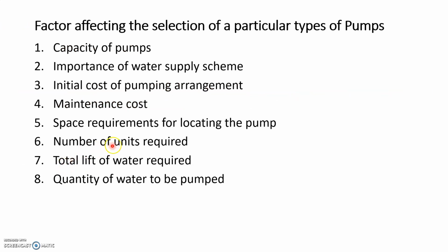Now there are certain factors based on which you have to select the type of pump you require. The first one is based on the capacity, whether capacity is large or small. Then the importance of the water supply scheme, how important that scheme is to you. Pumping arrangement, one stage or two stage. Maintenance cost. Next, space requirement, number of units required, total lift.